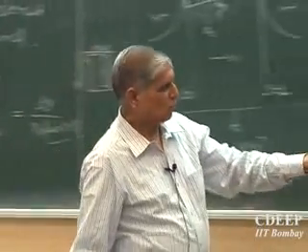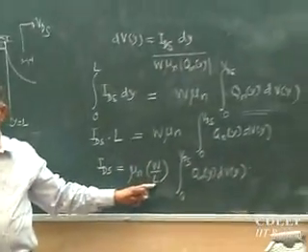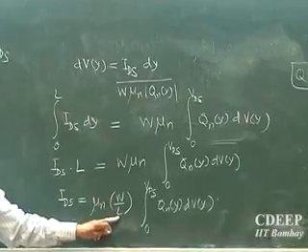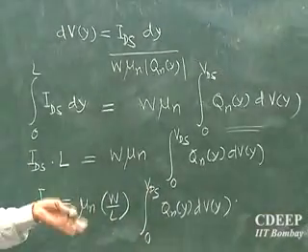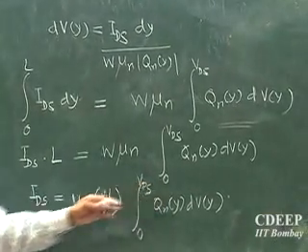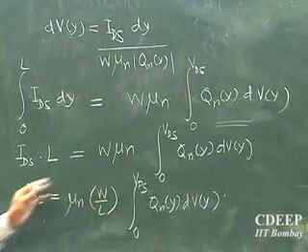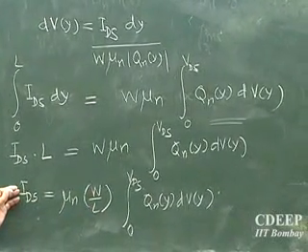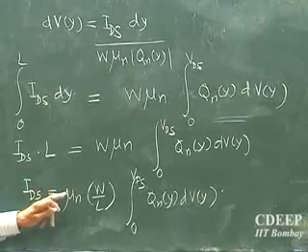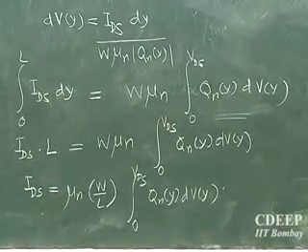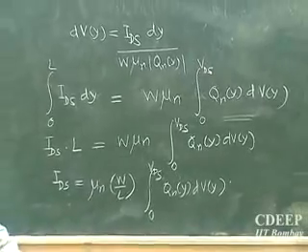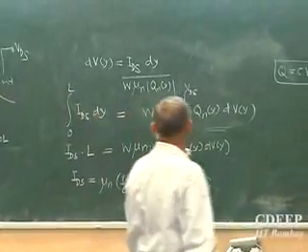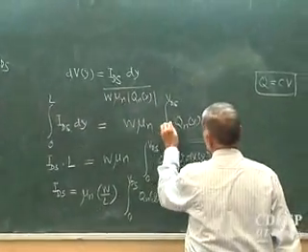So one thing I have said is that W by L normally decides the current. If everything else is the same, VGS and VDS are the same, this is constant, W by L will therefore increase the IDS. The other term which is seen here before I integrate is this mu n. In this integral, I quietly took this mu outside.